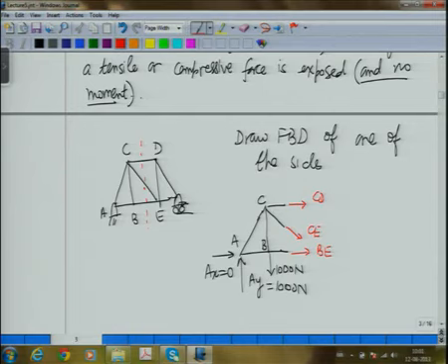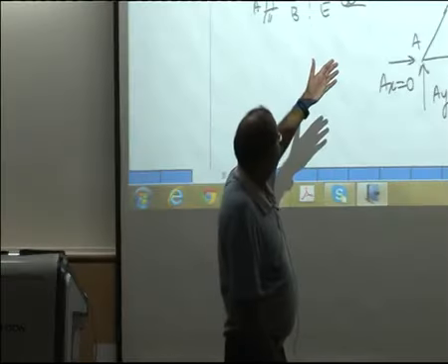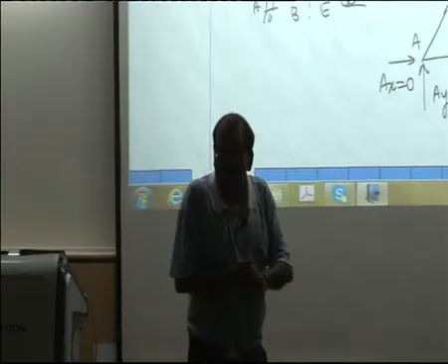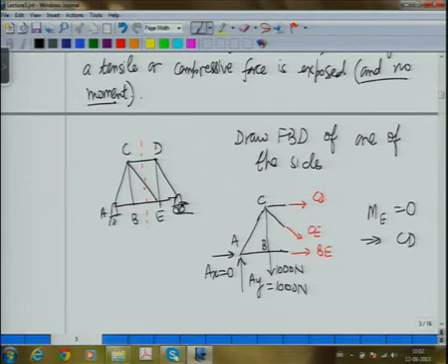So I will take, in this case, let's write this down. We take moments about E is equal to 0, and this will give me CD just in one equation. Once I get CD, then I can do sigma fx is equal to 0. That will give me a relation between CE and BE. Then I do sigma fy is equal to 0, and in fact, if I do sigma fy is equal to 0, I would have directly gotten CE. Okay, and then sigma fx is equal to 0 will give me BE.